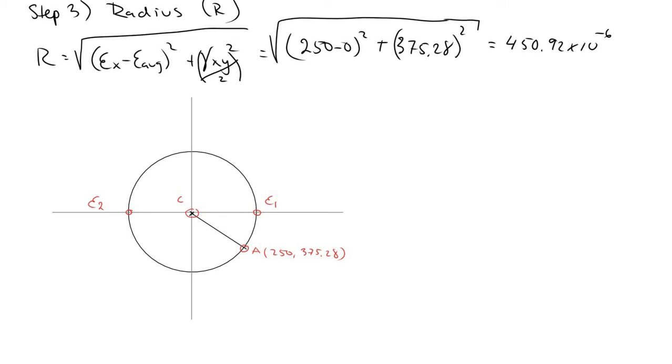Then we want to find our transformed element, which is from our reference point to our principal plane, or the normal plane. So from reference towards our principal, this is our 2 theta P1. And how do we find this angle? Well, it's quite simple from geometry.